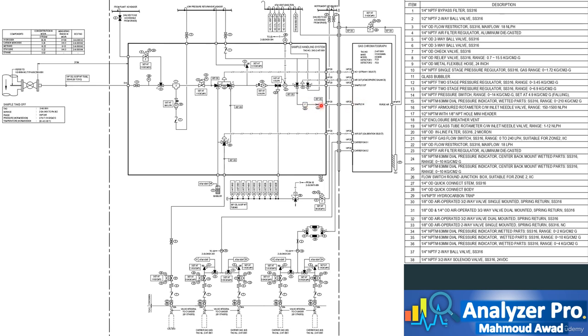The sample exits the analyzer through the sample outlet port, to be returned back to the sample conditioning panel and to the same atmospheric valve, then onward to the same low-pressure return header. For gas chromatograph, the atmospheric valve is needed to reduce the pressure of the sample to atmospheric pressure just before the sample is injected into the GC internal parts for analysis.